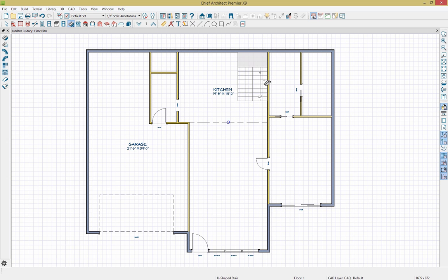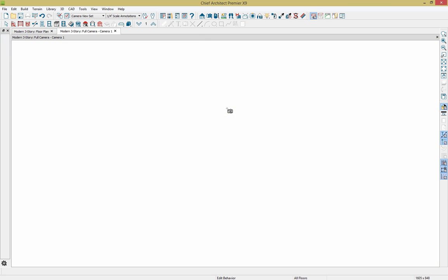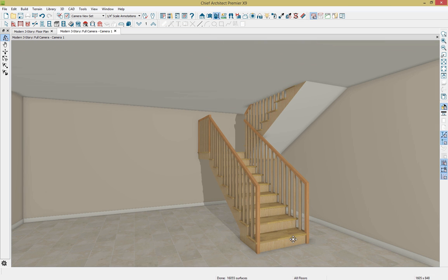If you bring it over towards the wall, the up will switch over to this right hand side, or you can bring it over to the left hand side. If you bring your cursor even further and go to this wall, it'll change the orientation. So it gives you a lot of different flexibility on how that's running. And then we'll just click once we're happy. And this time I'll be using our full camera. And that full camera is nice because we're going to stand in our room. I'll click where I'm standing and drag to my focus. So that'll bring us right into our space.